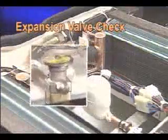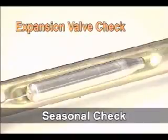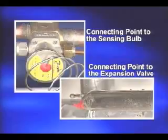The sensing bulb of the expansion valve should securely contact the pipe and should avoid contacting the air. The expansion valve should be checked every season. Check the connecting points of the pipes and replace the expansion valve when the connecting point of the sensing bulb is damaged.